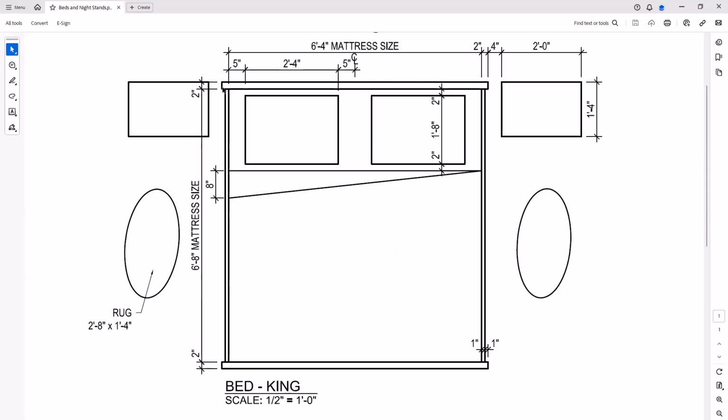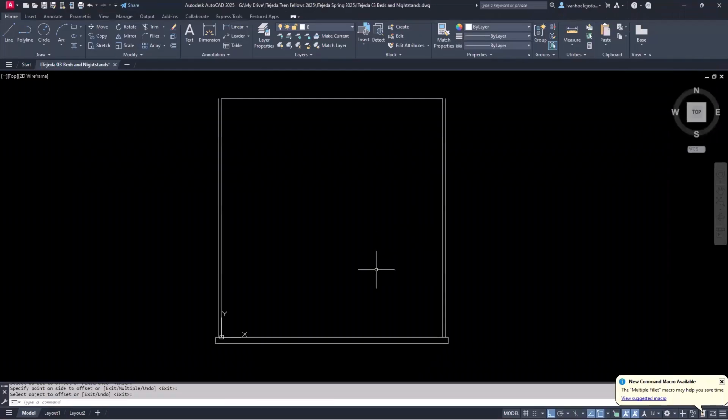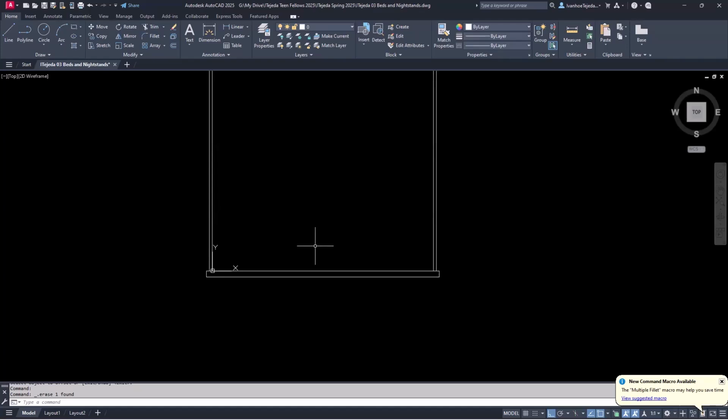All right, so now on the top, like I said, it's the same 2 inches. So it's a headboard, if you will, or just the part of the frame along the top, similar to the bottom. So I want to fix that. And what I can do is this. I can mirror all of the information down here. And when I do that, I'm going to have overlapping lines. So I'm going to take this line here, I'm going to select it and tap the delete key, because I really don't need it. And then I think what I want to do, instead of having to pick 4 separate lines, I think I want to use the join command.